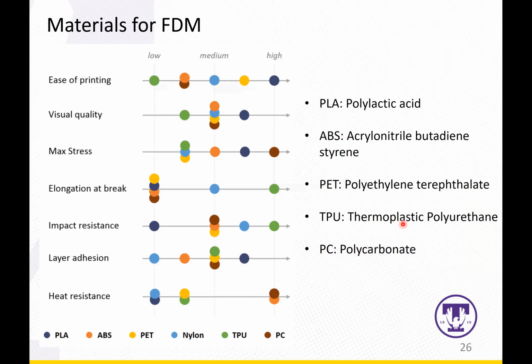You don't need to input values, you just need to select some options, but still to test all the combinations, whether I should heat up the platform to 40 degrees or 100 degrees, and what feeding rate to use for ABS or for PLA. All these different combinations, it took me a lot of time to get it to work. Actually, to be honest, my first Ultimaker 3 printing failed.